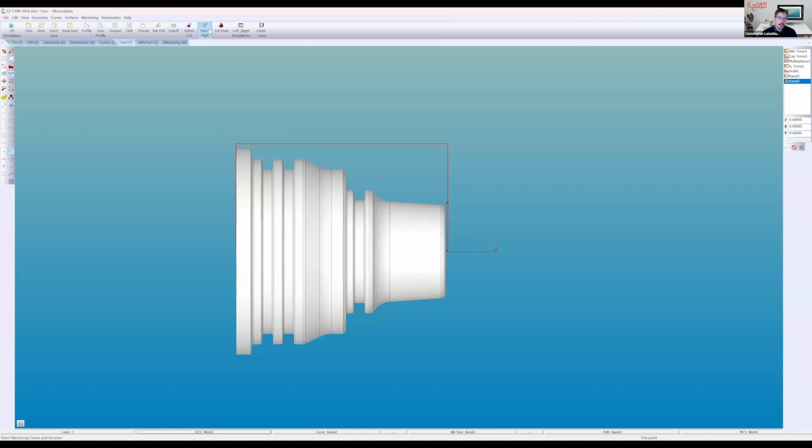So we'll go and use 3/4 view. This gives us the outline of the part. This is not a path. And as you can see, my cursor is grabbing certain areas. With snap to all, we grab intersections, lines, midpoints. So we're going to use left-right boundaries. We'll machine from here over to here.